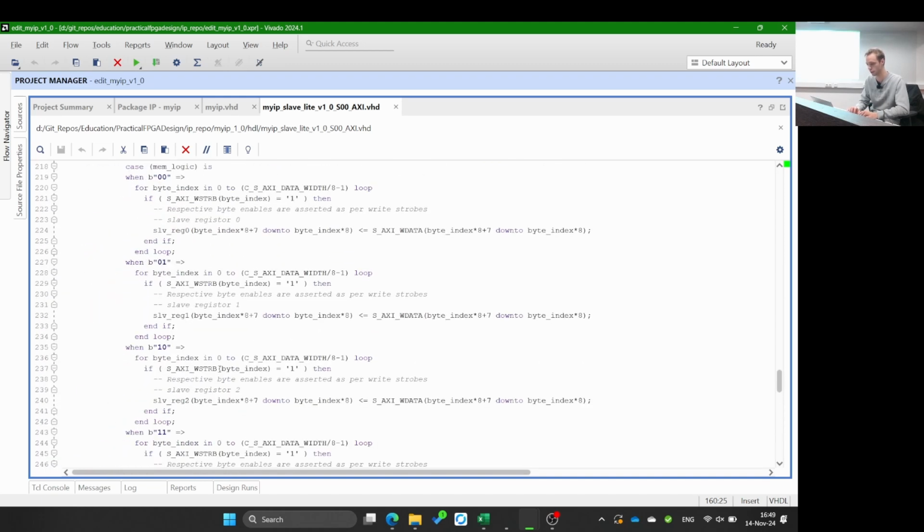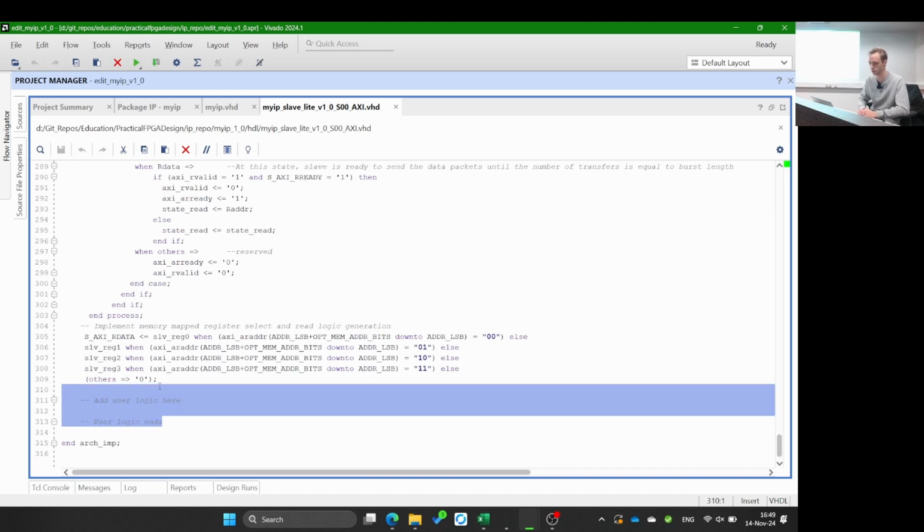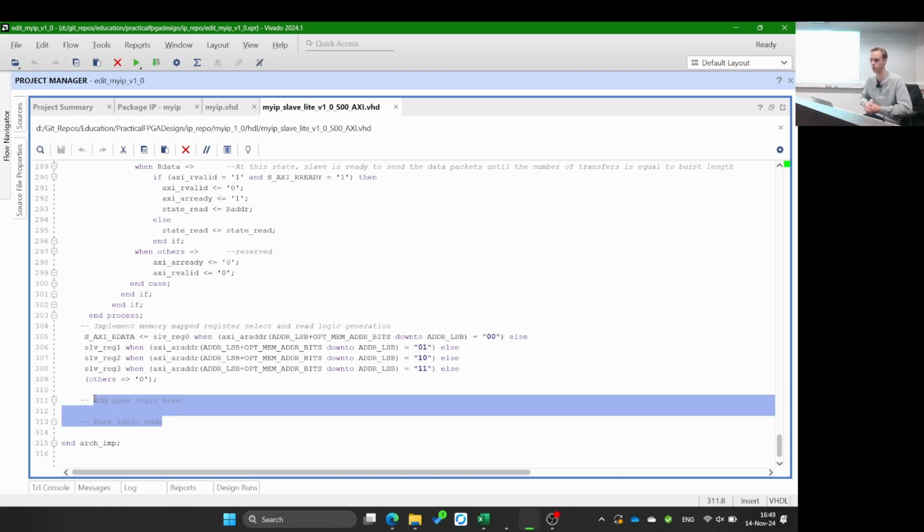What you need to add as user logic is to create or integrate the UART. Consider in your design if you need any buffer or FIFO, how that can be implemented, if AXI supports it, or if you need to add extra logic, or in which way you want to do that. So basically think a bit about how you could create the code. And the bonus task then is to implement the design blocks which you have described before, which should be okay to do because you have understood everything, but it might take some time to write the code and to debug and understand it actually.